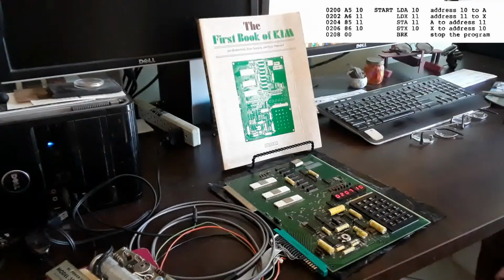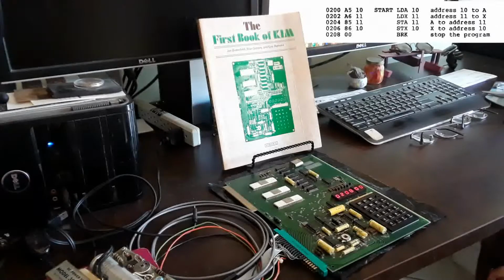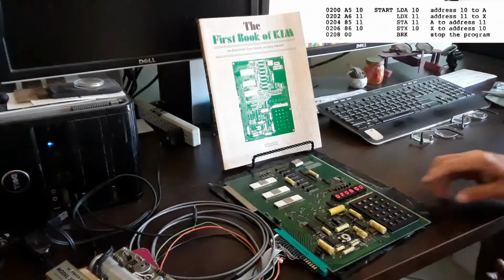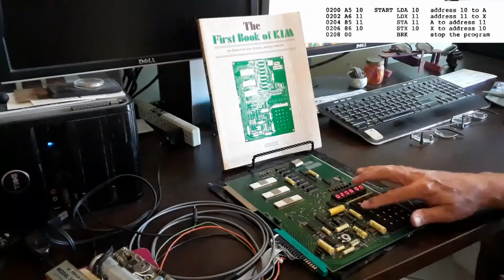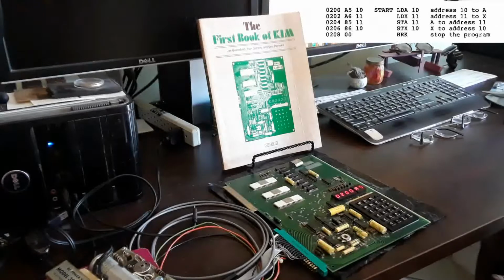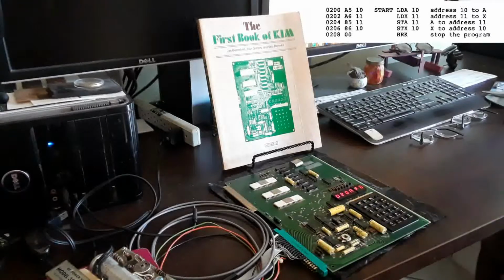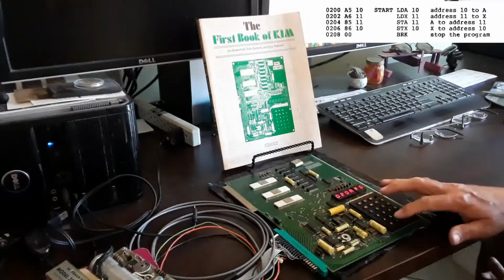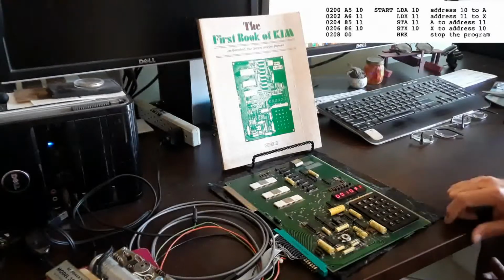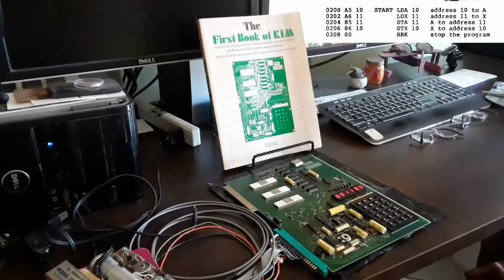Then we will end the program with a simple 00 or break command or instruction. Now, with the SST switch to the left or off, we have to actually go back into address mode and go to 0200, the starting point of our program, and then we can press go. Okay, now we can look at memory address 0010 and see we now have FF there, and if we advance by 1 we can see memory address 0011 actually has 00 in it, so our program works.